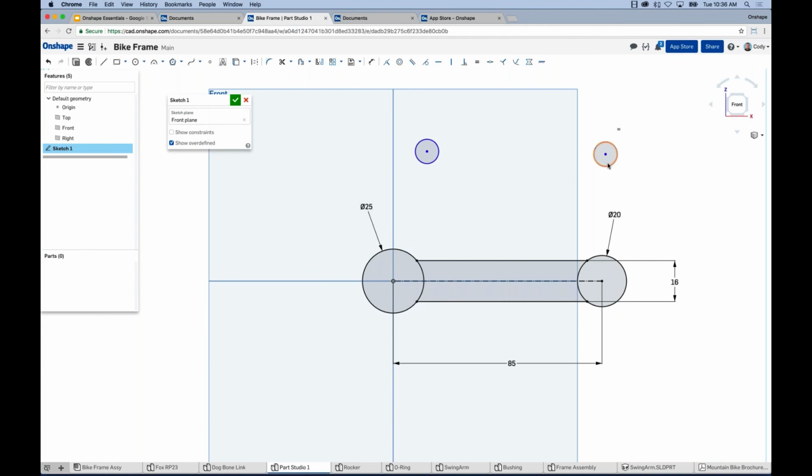So I'm simply selecting the geometry that I want to constrain, select the constraint from the toolbar. Now, if you change the diameter of one, they both change, right? It also means if I add a dimension to one, the diameter for both is defined. And it doesn't matter what the constraint is. That's all that it takes. You simply select the geometry involved, select the constraint that you want. I want this circle concentric with this circle. Again, left click, choose concentric from the toolbar.